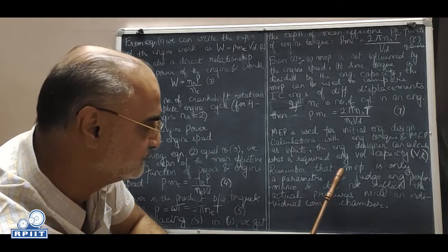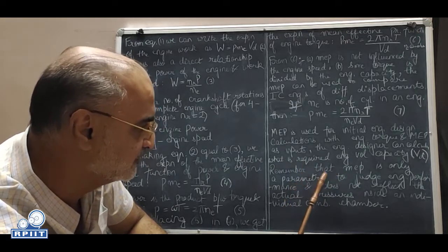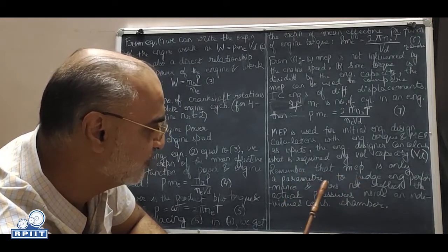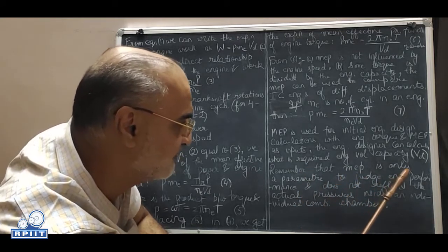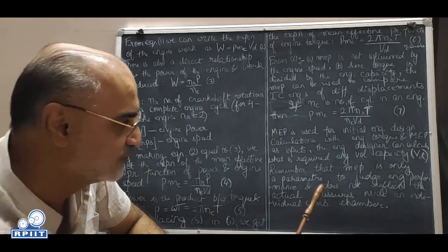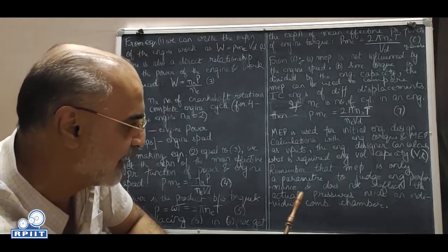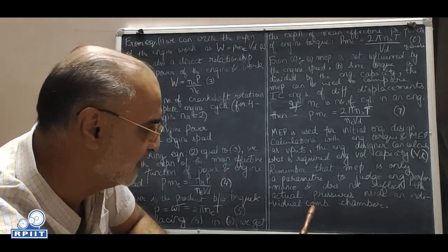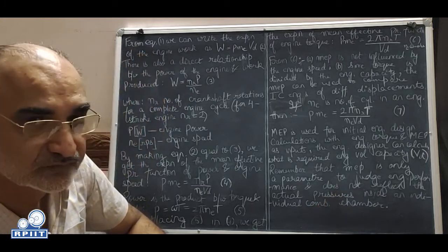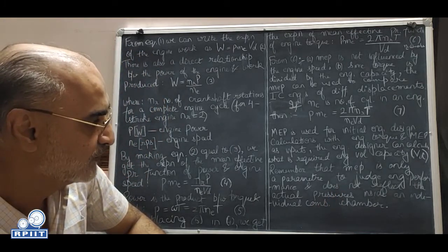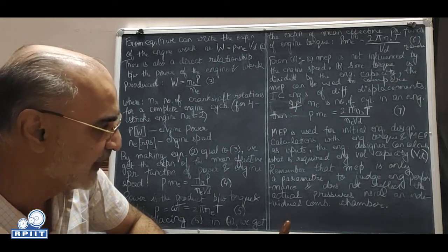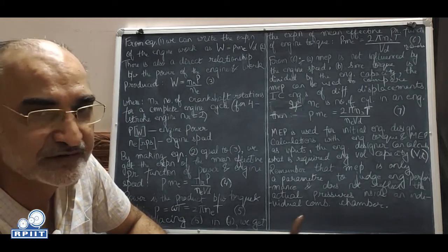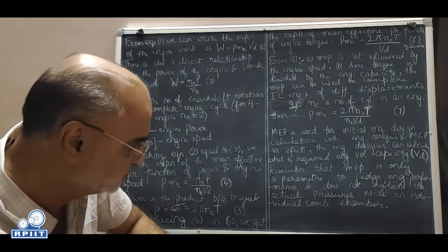The point to remember is that MEP is only a parameter to judge engine performance and does not reflect the actual pressures inside an individual combustion chamber. It is only a parameter for design purposes. It does not reflect the actual pressures. On some basis, the design has to be made.